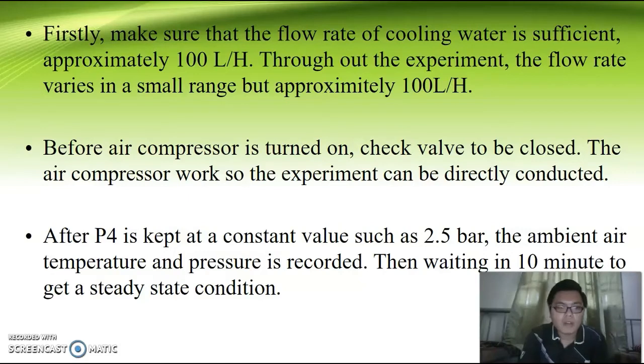After the pressure is kept at a constant value such as 2.5 bar, the ambient air temperature and pressure are recorded. Then wait 10 minutes to get a steady state condition. That's all about this experiment.